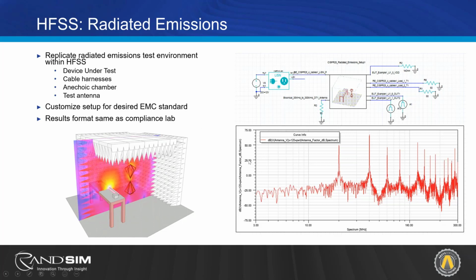This becomes increasingly prohibitive as you go higher in frequency. So when you start going above 1 gigahertz, this is effectively solving the fields throughout the entire 3-meter space for this example. You can imagine at the wavelength of 2 gigahertz, that's quite a few unit cells that are required to do the full solve. And in doing so, the simulation time goes up considerably.